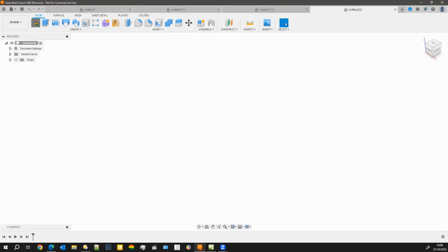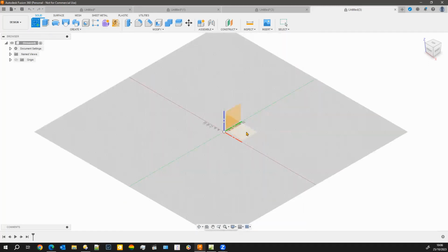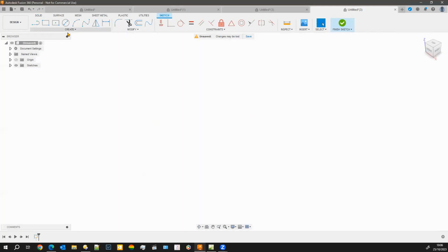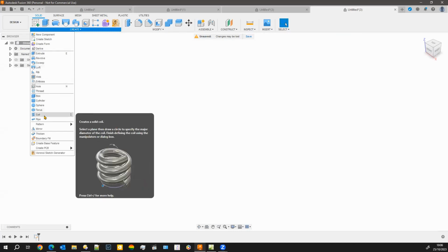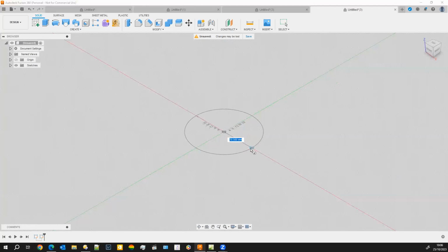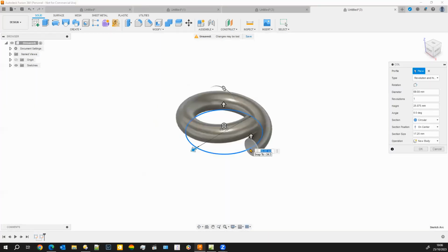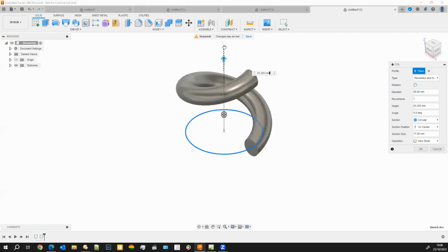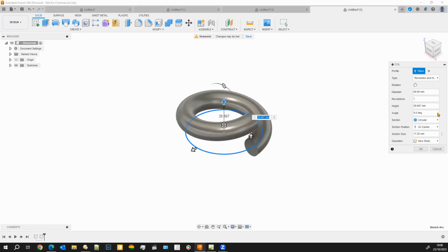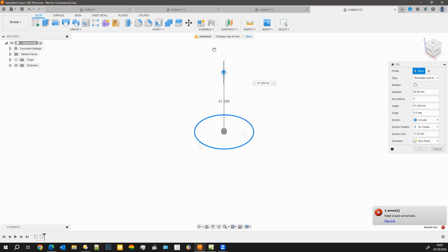The simplest way of creating it, I suppose, in one sense, is to, let's go back, finish that sketch a moment. And if we create a coil, and we'll create it on that face there. Now again, as usual, dimensions and constraints I don't bother with, because I'm trying to show you the principle of operation. So that adjusts the length, but we want more than that length in there. So the revolutions, now I'm just going to put in 15 to get us going.